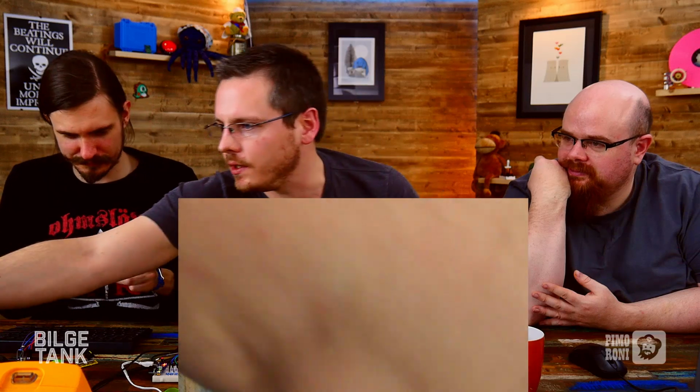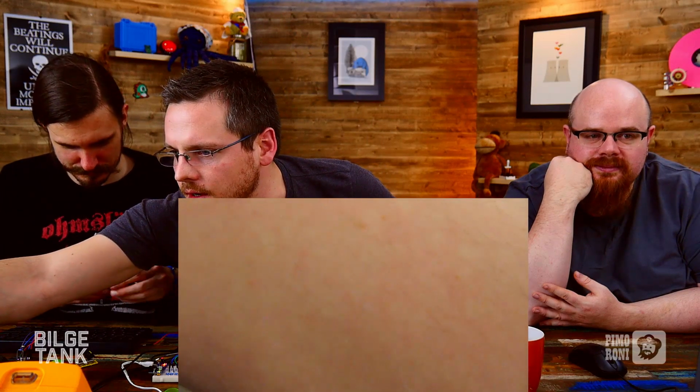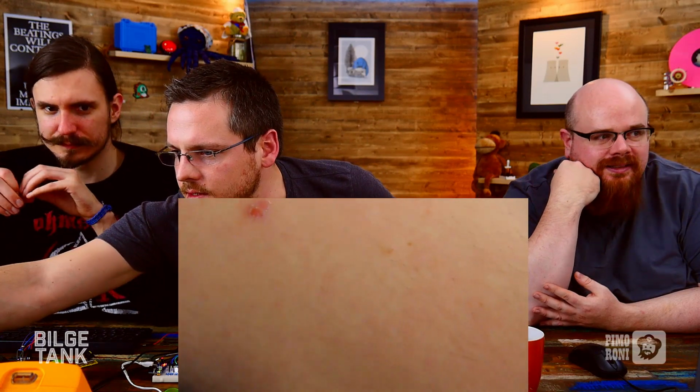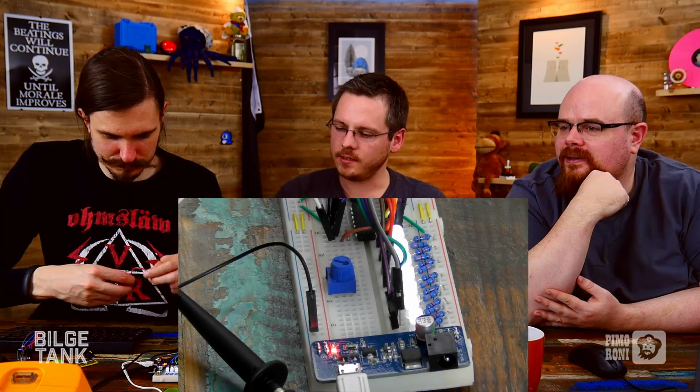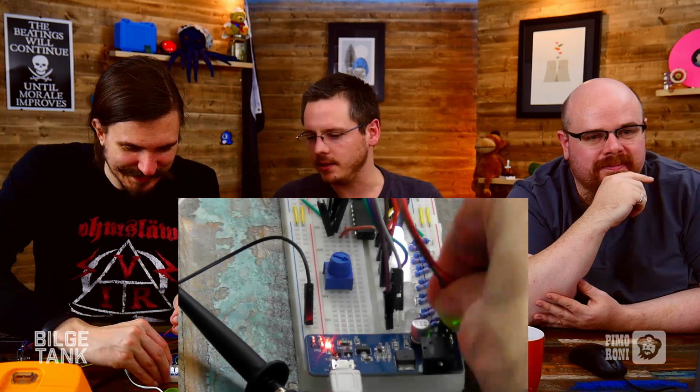But basically, yes, I can shift the offset. So at the moment we're offset by 1 volt. Whoa! So there, we've just moved the offset up. So now our sine wave is basically a little bit higher. So we're never hitting... These LEDs are inverted, by the way. So the on is actually 0, because they're sinking into the comparators.